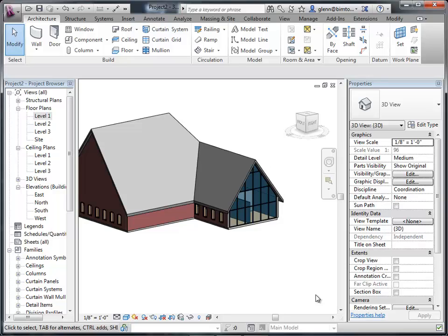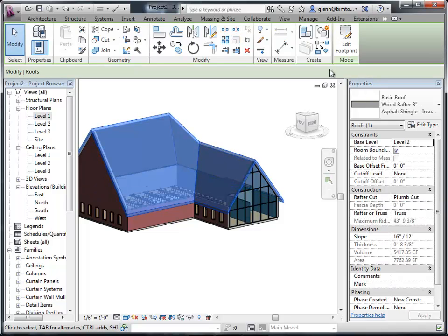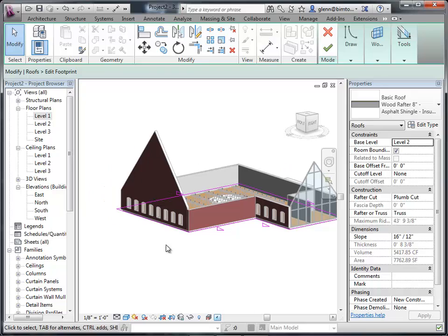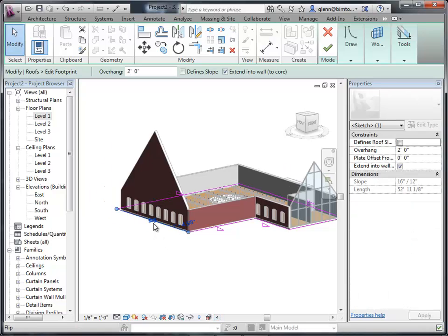No worries. What we did was, there were a couple of variations. The big thing was, when we went through and chose the roof surface, I chose the roof, and we said edit the footprint. There's the notion of the pink lines, and every pink line has the notion of whether it's sloping or not. So one thing I did was I removed the sloping. That actually sloped the roof up. That's the first piece.